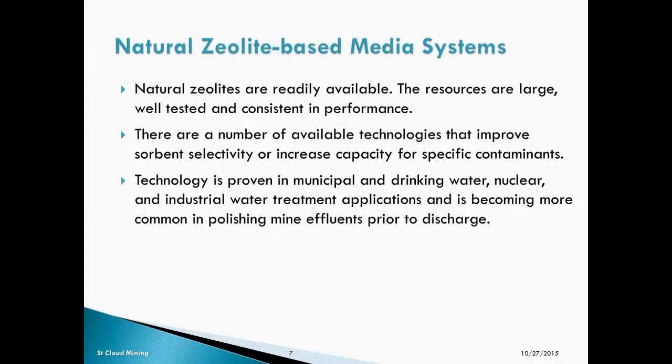And then we can change it, for example, a different way to make the zeolite very selective based on size for things like ammonia, even in the presence of what would normally be a cation, calcium. So we can take ammonia out of difficult effluents that have high concentrations of calcium and still retain the efficacy of the product.